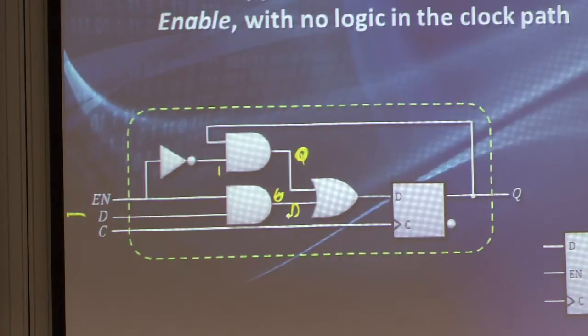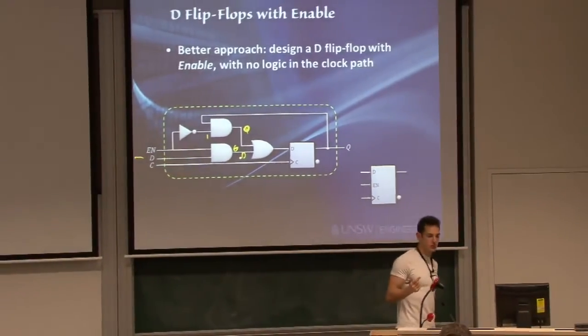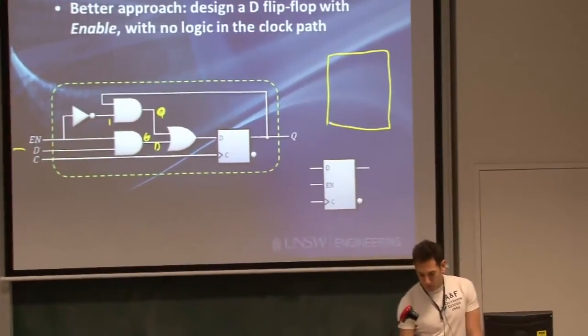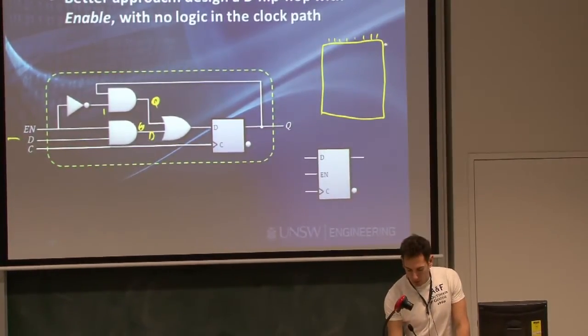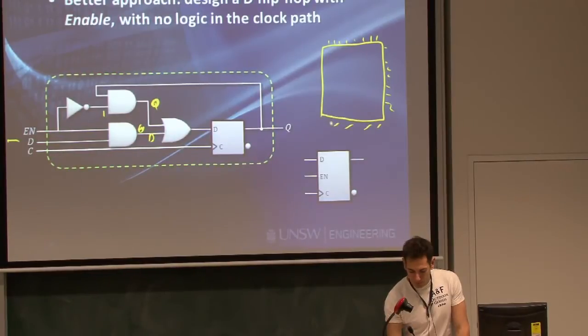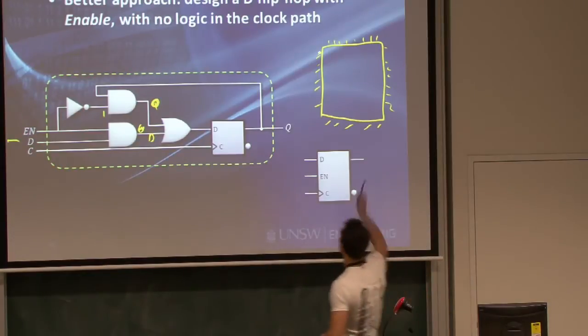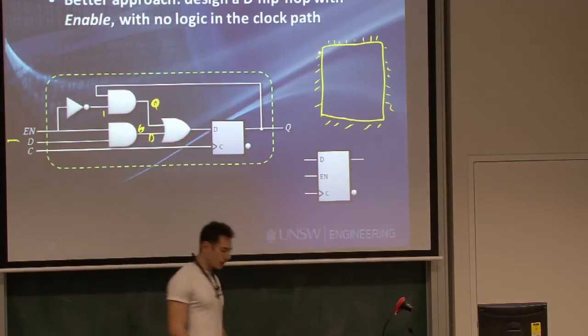Now, just taking this aside for a second, let me tell you about the clocking problems when we design a really big hardware system or digital system. Imagine you have some chip. So this is a chip and you have all the different input pins to it. And you have some registers and some logic in it, and you want the whole thing to be clocked at the same time.